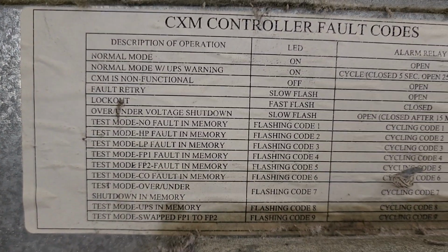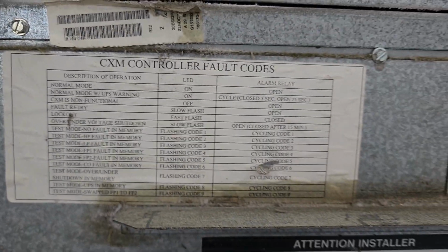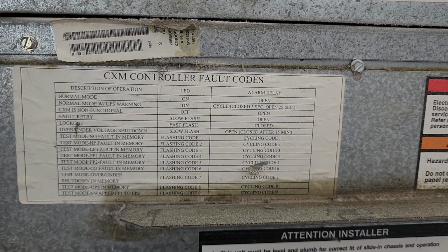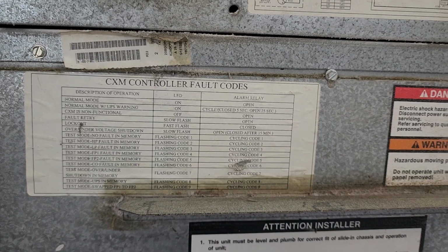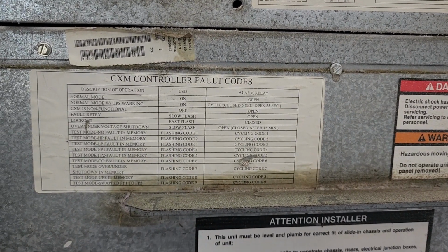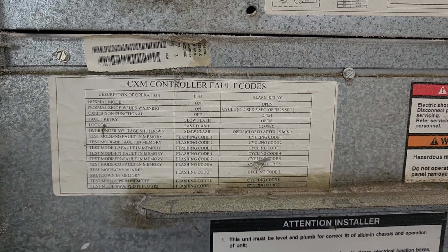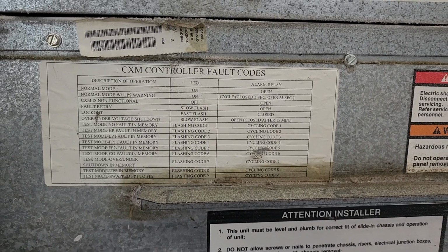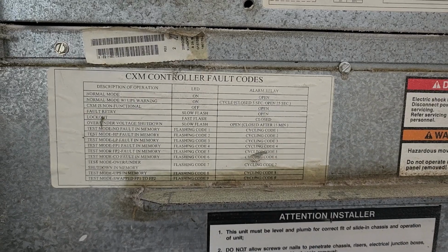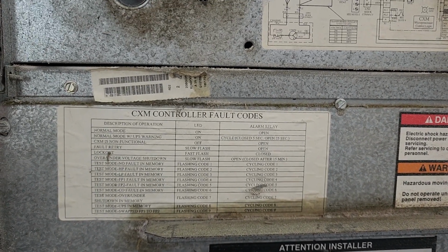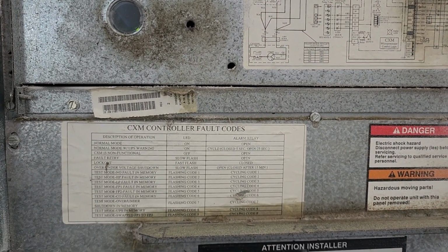Right here it says slow flash, over under voltage shutdown. Now that could be one of several things. Again, I don't think it's the power supply just because of the compressor, but there may be an issue with the board. At this point, from what I'm seeing, it's fairly unlikely to be the thermostat. What also could be going on is that there may be a short, or maybe the fan is clogged with dust and is basically causing an error when the fan tries to spin, and that affects the voltage of the entire system.